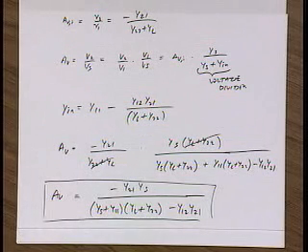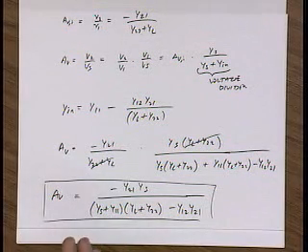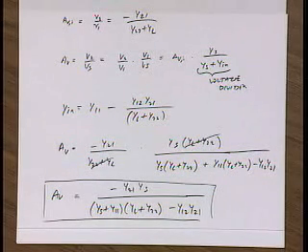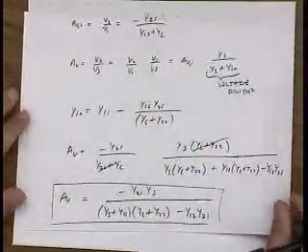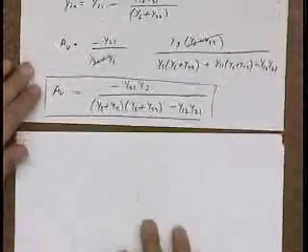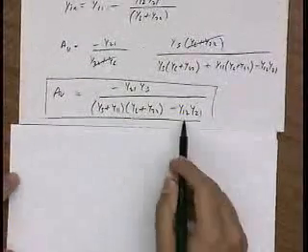Who cares about the gain? You can calculate the gain a million different ways, right? If you're desperate, you can write KCL, KVL, crank through the equations, and you have the gain. What you can't do with KCL and KVL directly is calculate the loop gain. Okay? So now if I look at this equation, I see that there is more information in it than I actually bargained for. Because I know that the feedback is due to y12.